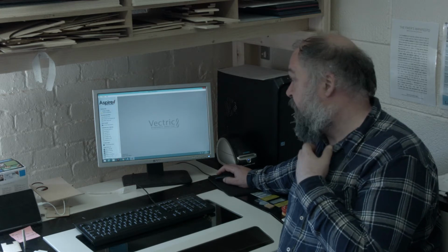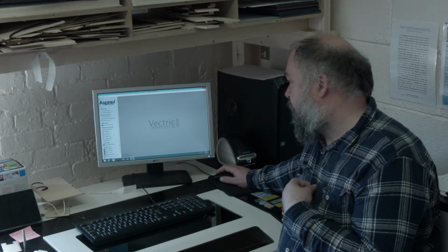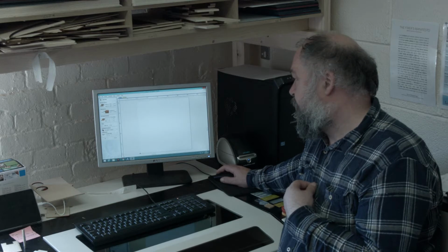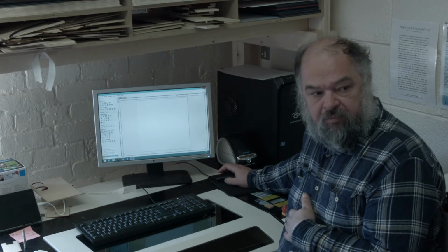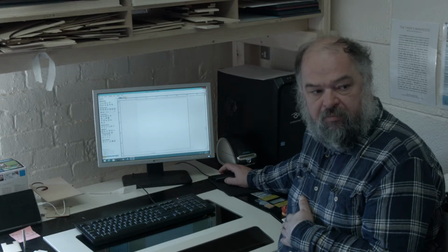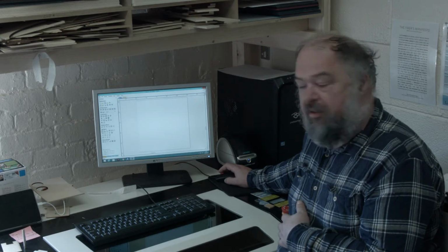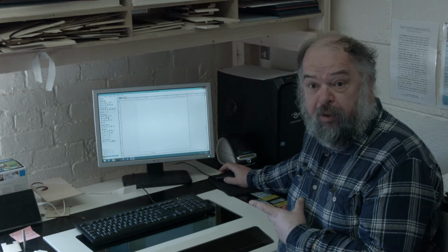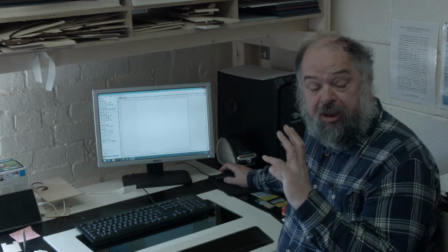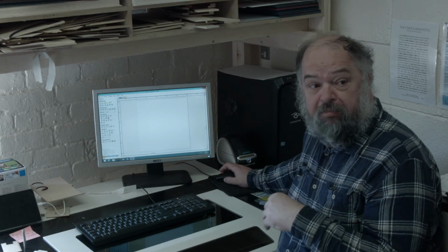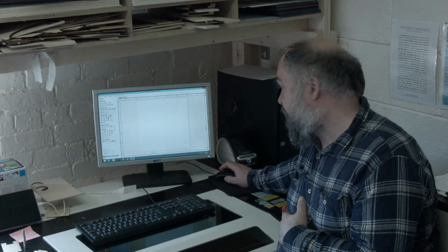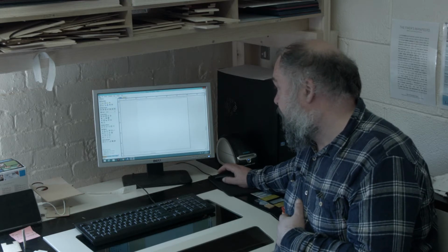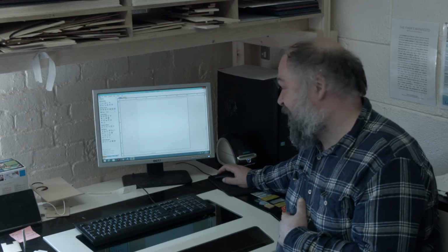You can take DXF. Basically, if you go into, let's create a new file. The only thing you've got to remember with the STLs is this software is working on 2.5D, not 3D. But the new version that is due out any moment now will do two-sided machining in one go, so you can do almost 3D. 2.5 plus 0.5, because it's not really.